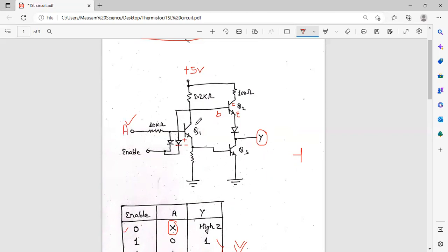That means this will be in the cutoff state. This transistor will not conduct because the base is not carrying any current. Then the 5 volt current will not travel here because here is another transistor, which is already in cutoff. So this is cut off, and then this also will be cut off, because all the 5 volt will go to the ground, as that is the easy way, whereas the other is a complex way. Although it goes here, it would make this conduct, but the current will be stopped even from here, because its output is connected over here for the conduction of transistor Q3.